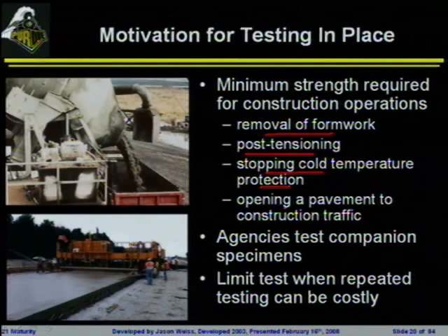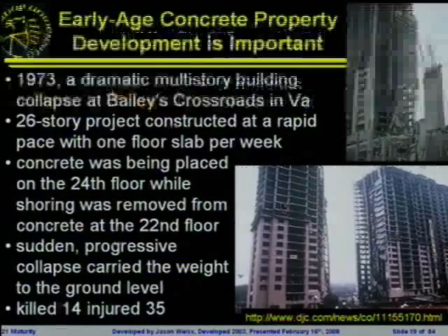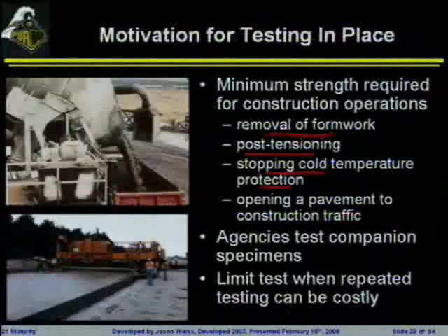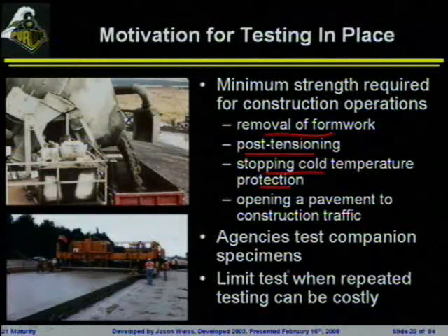And some of these are things that people are very eager to know because it's going to change the construction process. Post-tensioning. When can they release the pre-stressing on a beam? When can they strip the forms? When can they open a pavement to traffic? They want to be able to calculate this fairly quickly and don't necessarily want to just sit there and test beam after beam after beam and try to guess at when they're going to get enough strength.